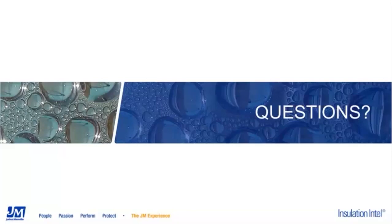Thanks, Kim. Well, we wouldn't normally make a recommendation to use an item like a wood block when there is definitely an opportunity to support the pipes in a better way. We have the Trimer rigid insulation in a variety of different densities and strengths, and we routinely help different specifiers and contractors with pipe support calculations. So in those cases, we actually can help determine what grade of Trimer to use at the pipe supports.